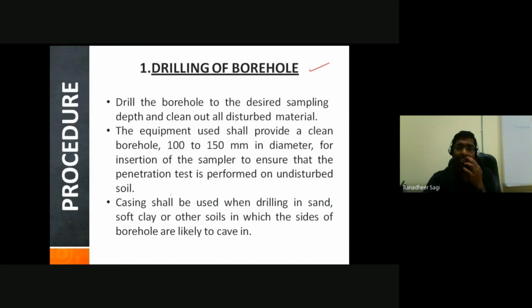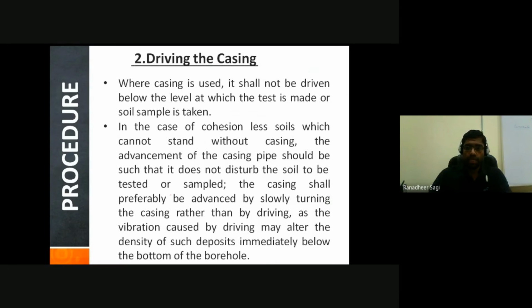Okay, so why the casing is required? If the casing is not used while extending the borehole into your sandy soil deposit, or even in your soft soil deposit, so the surrounding soil gets collapsed, you are going to see a cave formation happening into the borehole region what you have extended. So next is driving the casing, so that if this is my borehole what I am trying to look at,